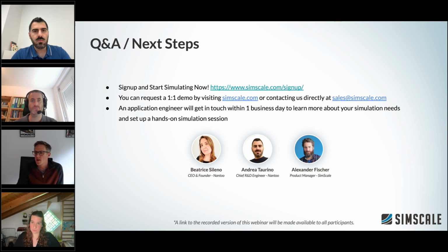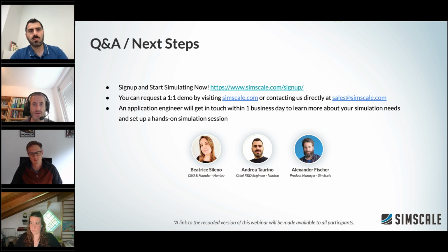Great, thanks. Very briefly, I see one question we can answer very quickly: does SimScale have an API, which I think you touched on before? So yes, sure. That is just standard, right? Obviously, Andrea mentioned some of the things that are important in how to set such a case up, right? So it depends on the repeatability. How do you set up the geometry? Do you have the identifiers? Often it helps in your CAD tool to really name the faces and bodies with specific labels, as it's not always easy to replace one CAD with the other and keep all of the assignments.